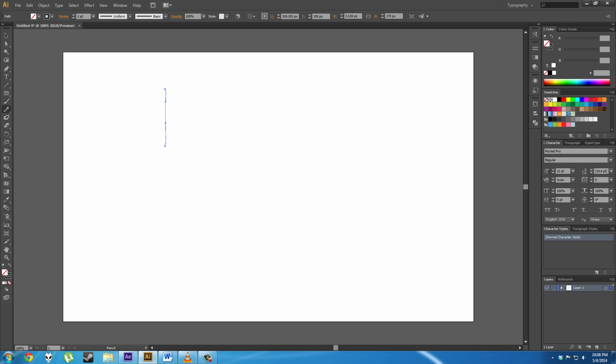With these kind of letters, we want each path to be separate because these letters are made up of different parts. So what we're going to do is press V, click somewhere else on the document, press N to bring back up that pencil tool, and then keep drawing. Now, since the cursor is far enough away with this selected, we can continue drawing. We only need to deselect the current selection if the two objects are close enough together. So, I will draw this out.